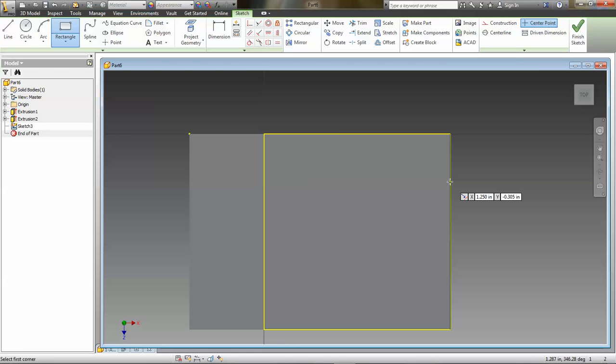So basically what I do is I move the mouse down to approximately where it should be, and then I look at the y coordinate and I know, well, that needs to be like -0.5. Okay? Click the mouse, and the notch is going to be about that big, so I look at my dimensions and I say, oh yeah, well, clearly the x coordinate is 0.75 and the y coordinate is 0.25 because it's 1/4 inch by 3/4 inch. Click there. There's my profile.